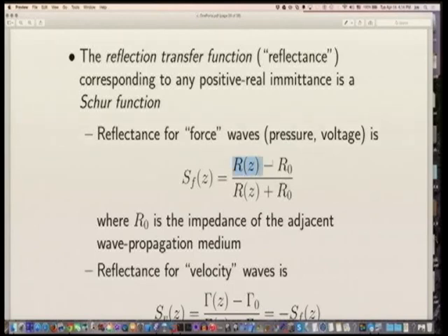And you see the 0 right here. You get R0 minus R0. So that is the so-called matched impedance case. And this is what we do in our Ethernet wires, right? All of our Ethernet cables have these little terminators that are the same impedance as the characteristic impedance of the coaxial cable, so that the Ethernet doesn't have a lot of reflections. You want to send packets out over the Ethernet and have them not come back. You want them to progress, reach all the computers on the network and then hit their terminations and disappear.